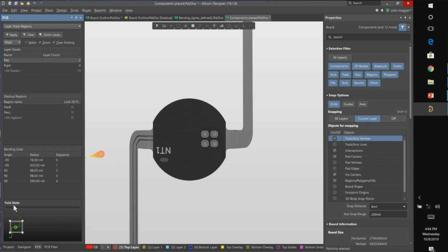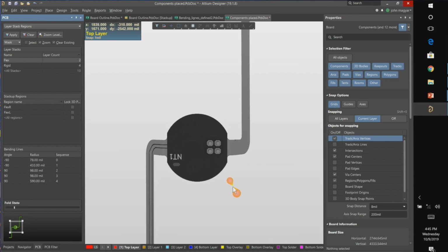So when you're drawing the bend lines, what kind of keep outs or DRC rule things can you do there, especially if you're dropping components near that region? Is there anything that will protect you from trying to put things where bends are at? Right. You could place a regional keep out. When you place a region these days, I think it has a property to be listed as a layer specific keep out, or you could have all layers.